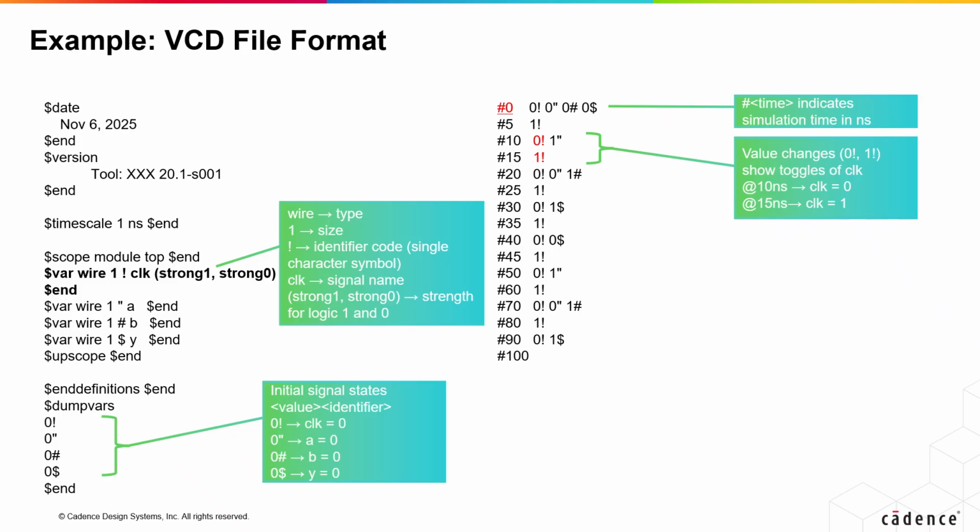The observation window is determined by the timestamps in the VCD file. The first and last timestamps indicate the start and end points. Here, it begins at 0 and ends at 100. This information from the VCD file will aid in calculating the design's power.